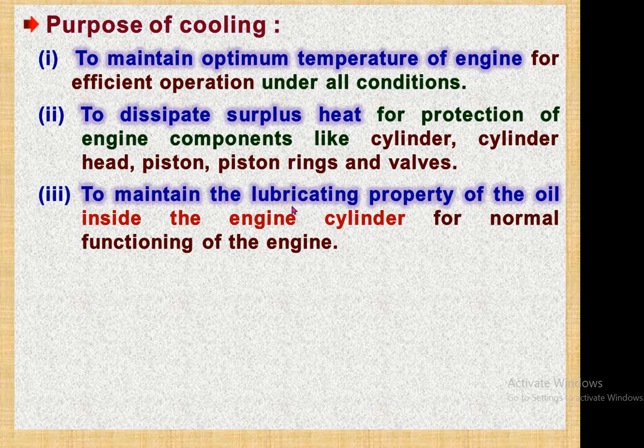Now third, to maintain the lubricant property of the oil inside the engine cylinder for normal functioning of the engine. As we know, if the temperature of the system goes up to the highest range, then it will damage the property of the lubricant, or it may decrease the lubricating quality of our lubricant oil.